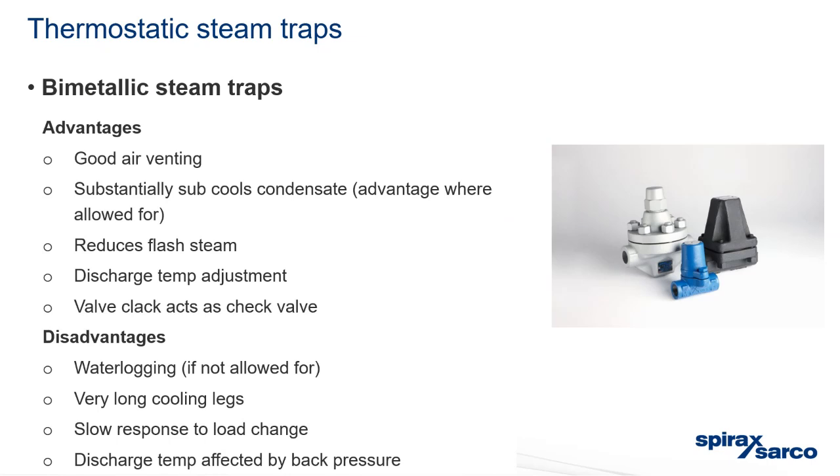Disadvantages: waterlogging, as we said before, very long cooling legs. So these require a longer cooling leg than the previous trap. Slow response to load change. So yes, they tend to work best where you have a constant load. And discharge temperature is affected by back pressure.